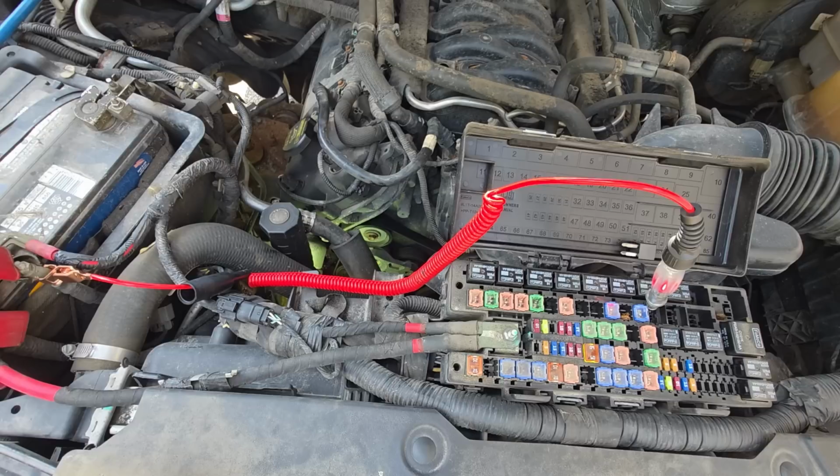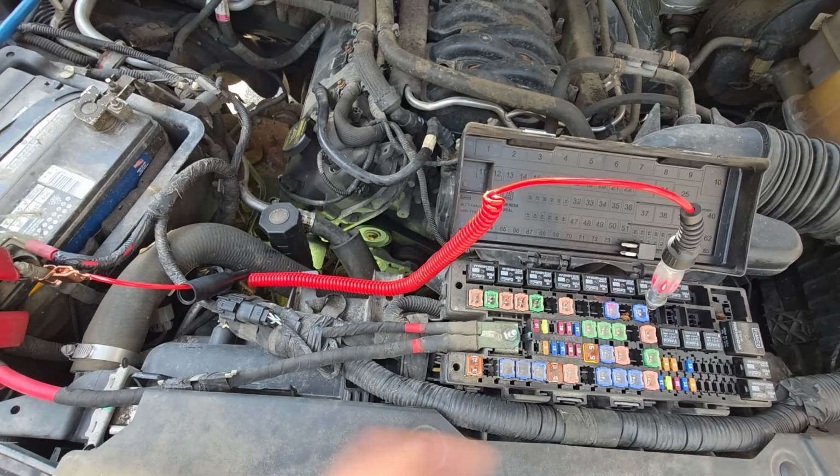Right, let's go. So the beautiful thing here, Rick, right off the bat, your clutch is fine. We have a wiring problem. We can fix this. That's what that means. I mean, that test right there, I was going to pull the relay tool out, but I don't need to. This is good enough to tell me right now if we put this back on, your AC is going to work. I don't care about that because I can use this now as my guide for the rest of the troubleshooting. Everything else we do here is engine off stuff. I just have to find where that open is. And sometimes if you disturb things too much, you'll mask the problem and you'll never find it. So I want to be real careful with what I'm touching.